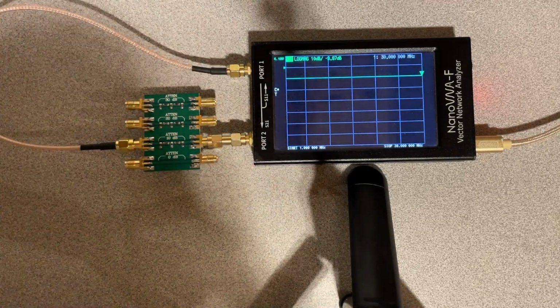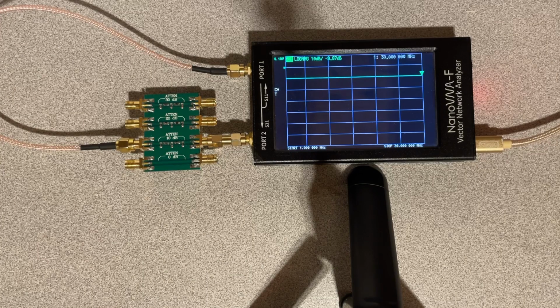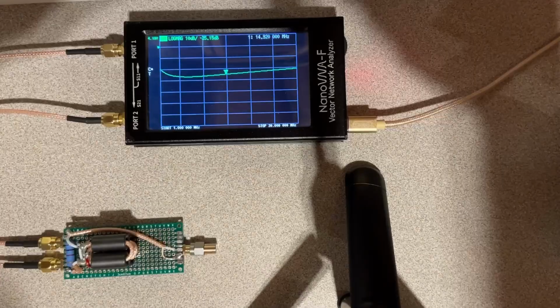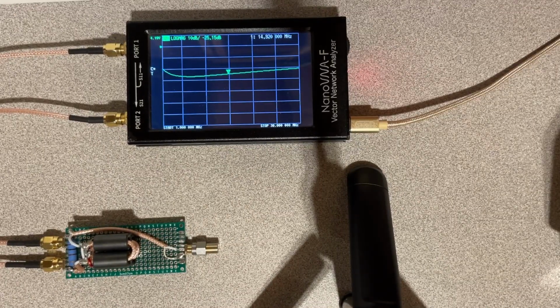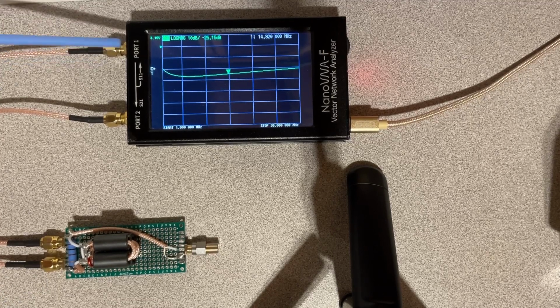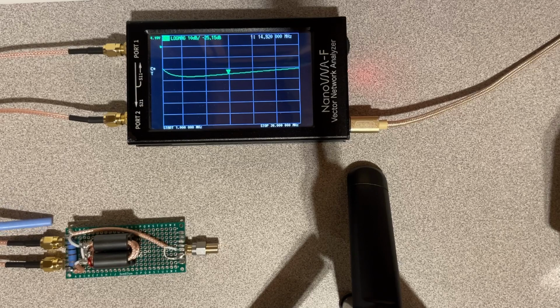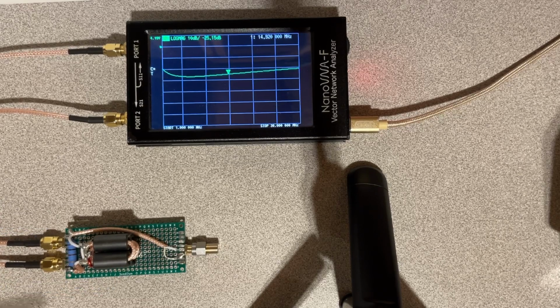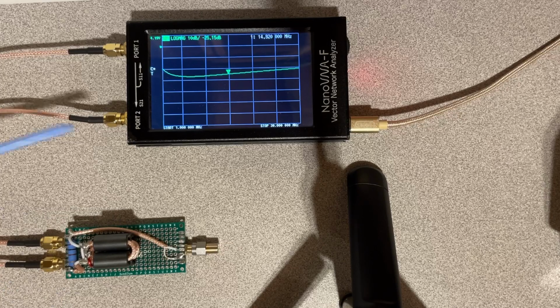Next, we're going to go ahead and measure the isolation between the two ports of the splitter combiner, and then we'll measure the SWRs. All right. So now we're taking a look at the isolation between ports 2 and 3. So what we do is we take the output signal from port 1, we connect it to port 2 on the splitter combiner, and then we take port 3, we connect that to port 2 and see how much of that signal we're receiving. So a good design should be at least minus 20 dB, which is 100 times lower.